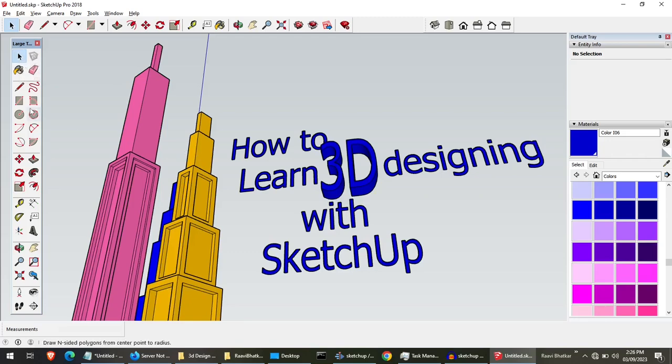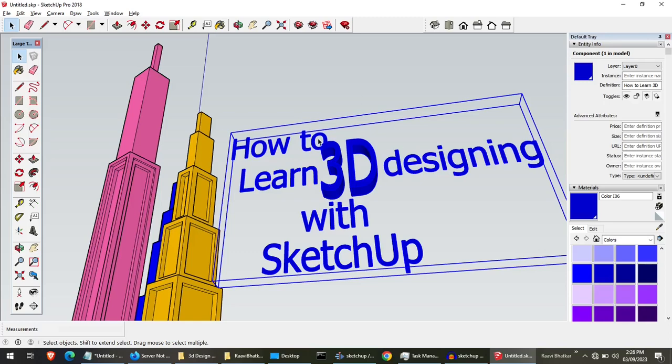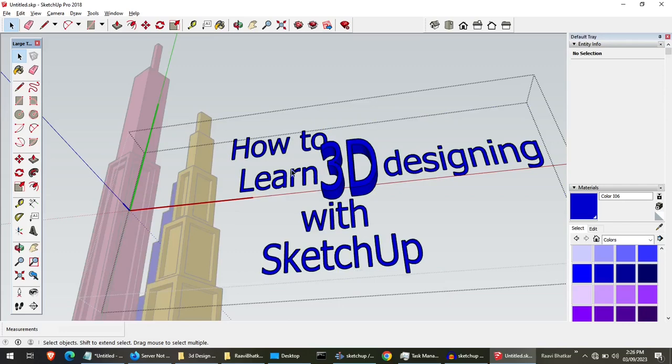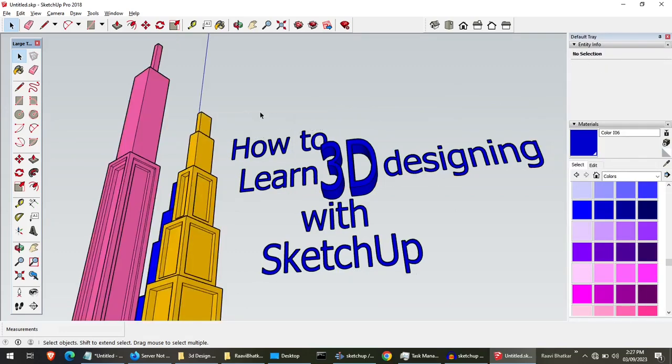Using the select tool, you can select it by double clicking it. When you click it sometimes it will select the whole component. When you double click it, it will break it and you can select each different component. If you want to select this building and it is selecting only one side of it, you have to double click it. It will select the whole face including the edges, but if you click it 3 times, it will select it completely. For selecting, you will use this select tool.